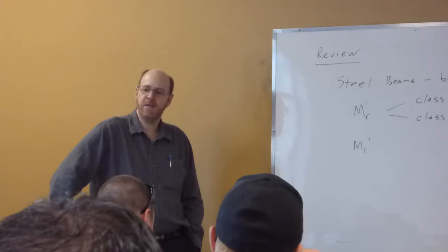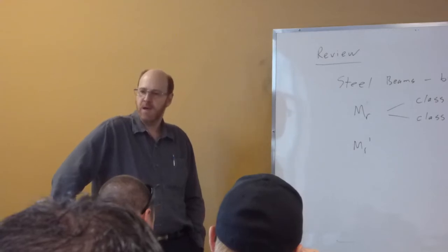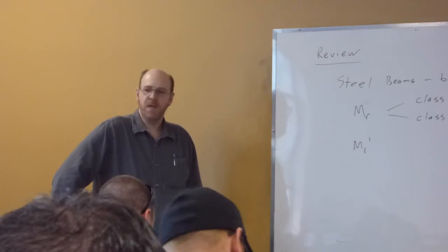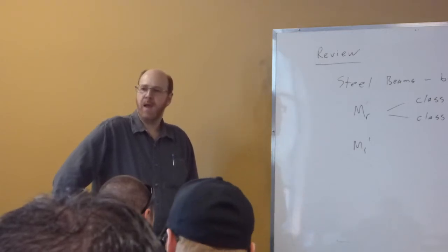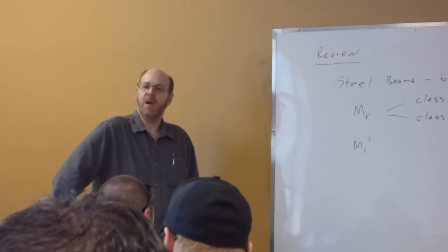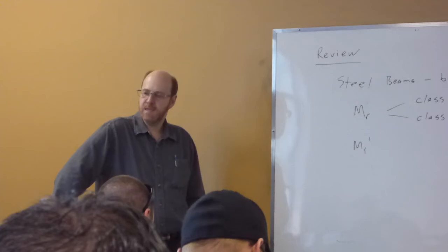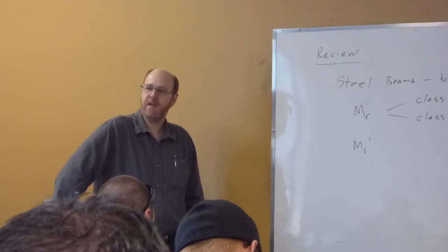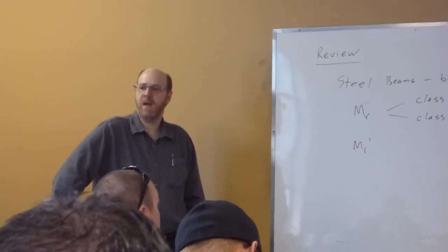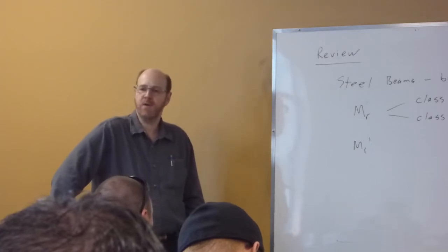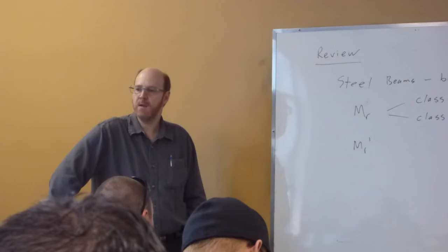But rather than calculate it in terms of stress or force, like we talked about in our strength of materials course, what we're doing here is coming up with a force divided by resistance. Right? So there'll be a PF divided by a PR. And that number should be less than 1 by itself. Then we add in a bending, MF divided by an MR, right? We can do that in both the X and the Y direction. And we add both of those together, and if this whole thing is less than 1, then we have something that works.